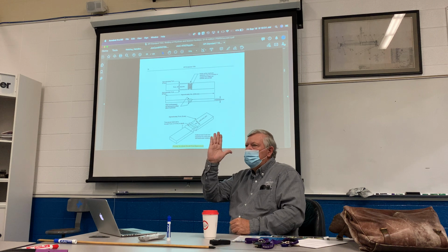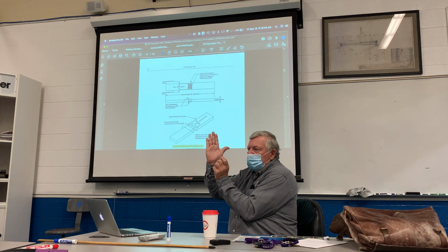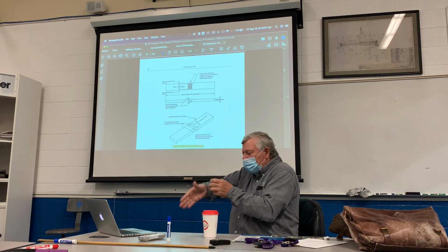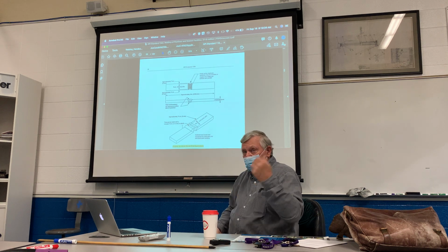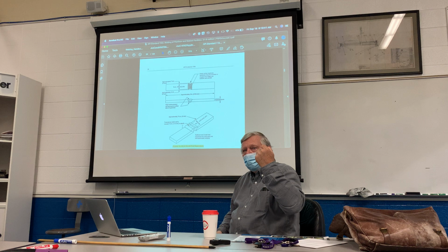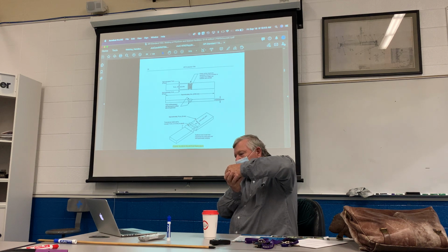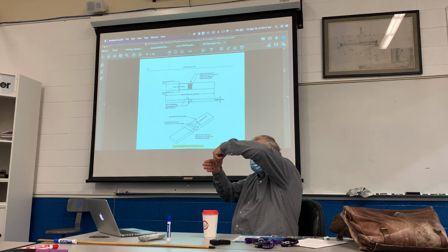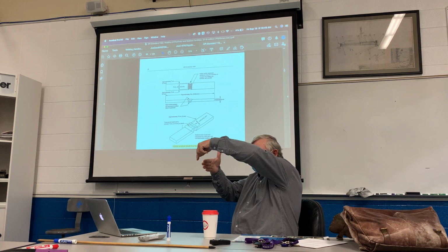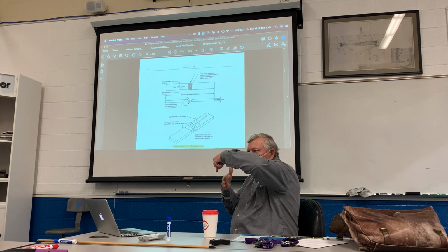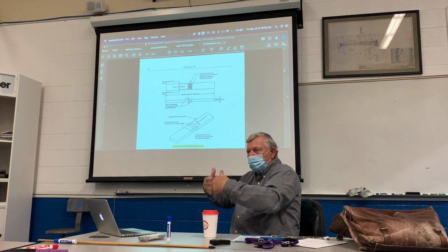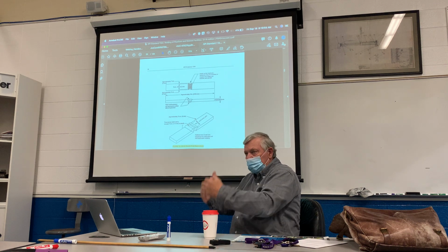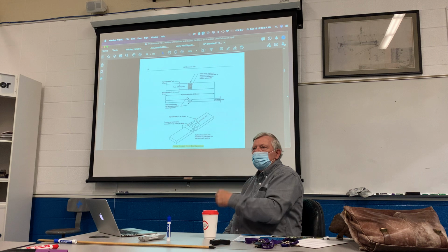So now you have this piece here, you have the weld, and you have a little stub of the coupon. So what I do is I have them put it in a vise, and then I take a torch, and very slowly I will just go across that nick break and cut it. I'll just slice through it, back and forth. Just let that metal roll. It'll just melt off of that nick break. And I can tell if there's anything in it.